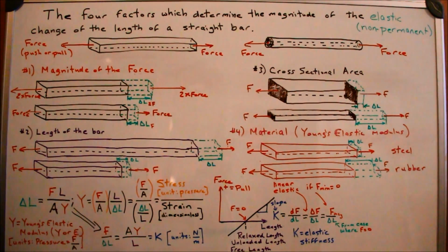So if I just take these terms and rearrange, I can rearrange that to become the cross-sectional area times the Young's modulus divided by length. And this has units. Stiffness is, for a force, how much deflection I get. So it's a force over deflection. So this is the definition of elastic modulus, and you can see how stress, when I apply a stress on something I get a strain, and how stiffness, they all relate back down to this basic equation. So you can remember it in some forms. I think it's easiest to just remember that and then remember these definitions following it.